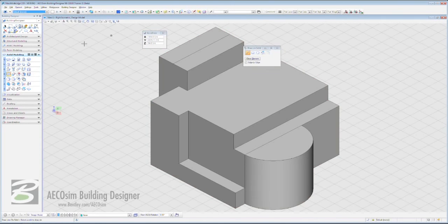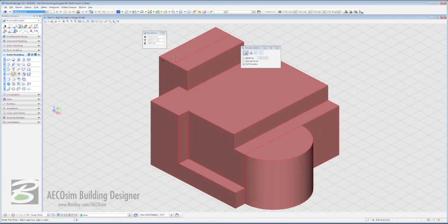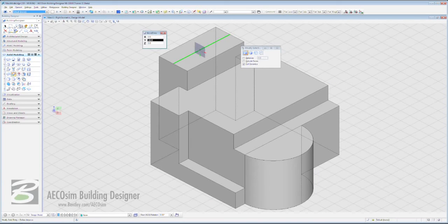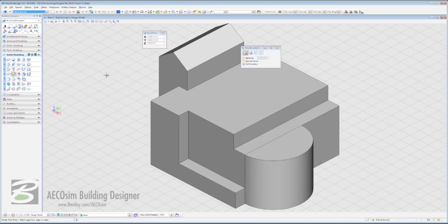We're going to place that line there and then come back once more to modify and just click on the line itself, because we're going to be putting in a hipped roof onto this particular roof structure at this moment in time. We can always change it in the future at any time we need. But at this moment in time, design scope, design options, we're playing around with them. We're going to raise this one here and just left click to accept.